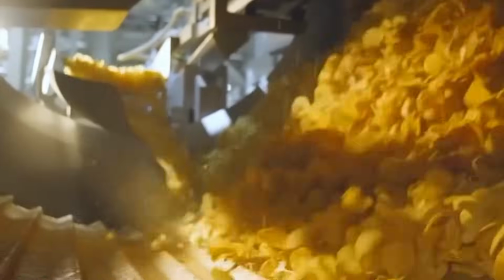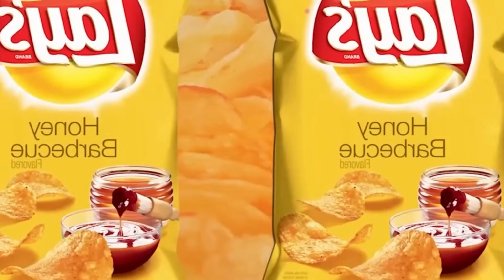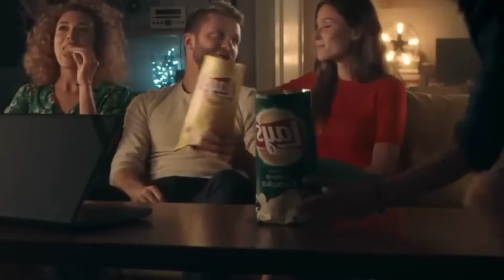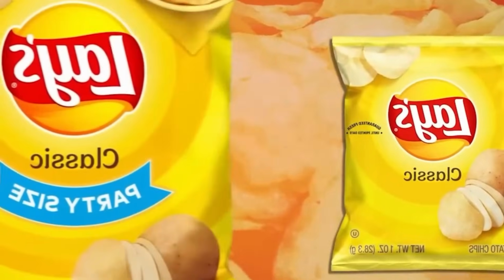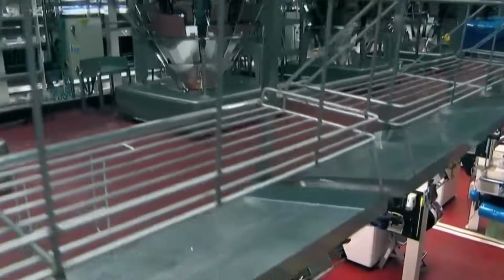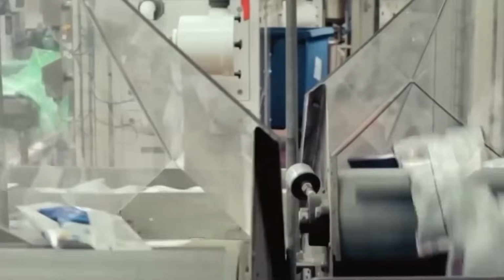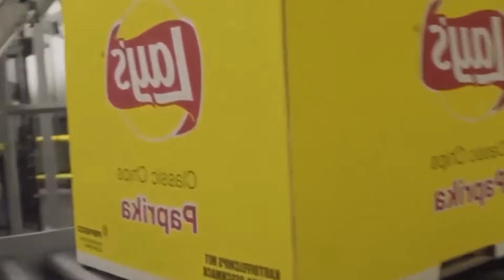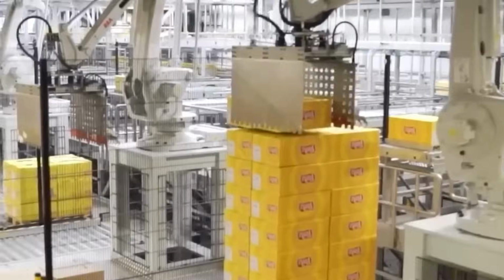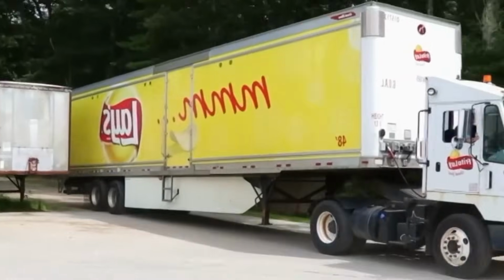As the chips exit the fryer, they pass through an oil removal system consisting of vibrating conveyors and high-velocity air blowers or centrifugal de-oiling drums. These reduce surface oil, improving shelf life and texture consistency. The chips are immediately cooled by ambient or chilled air using tunnel coolers that bring the product temperature down below 40 degrees Celsius within 90 seconds. This cooling step also halts cooking and stabilizes texture.